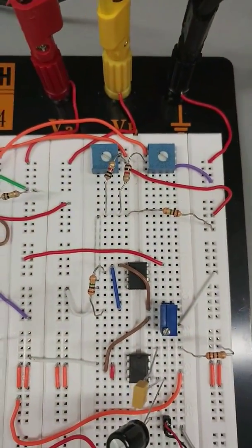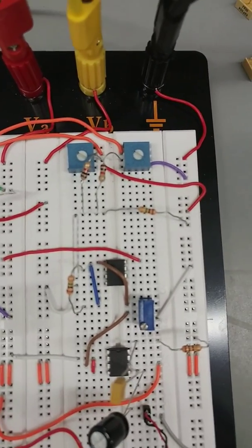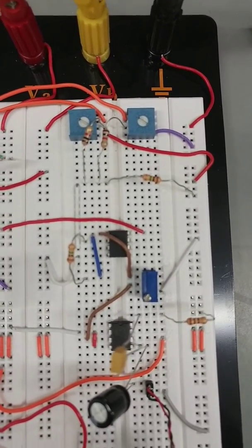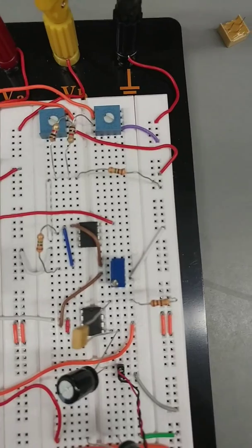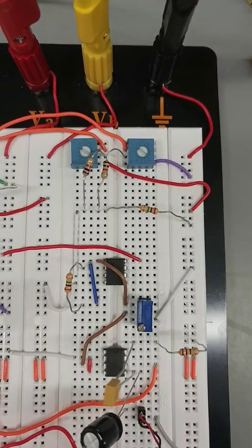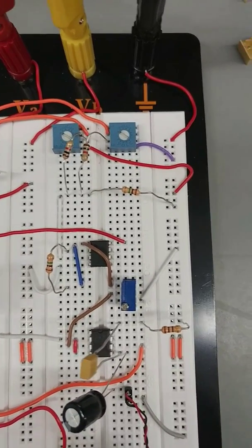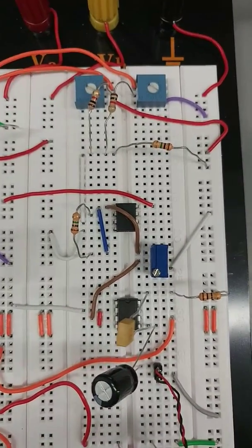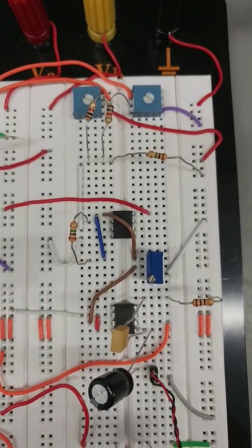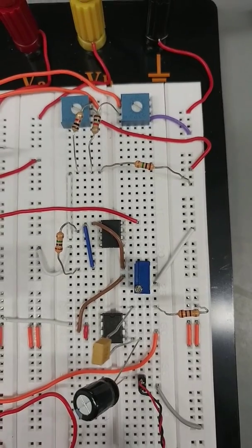The input on the left hand side is V01 into a 1 meg pot, then the 10K, then the 1 meg that goes to ground is right there in the bottom right hand corner, and the other pot for the other input, the 10K, then that gets fed to the TL082, just one side of this IC this time.